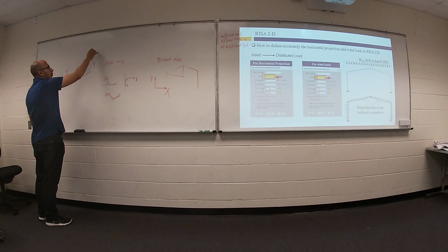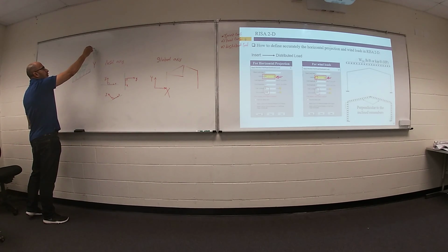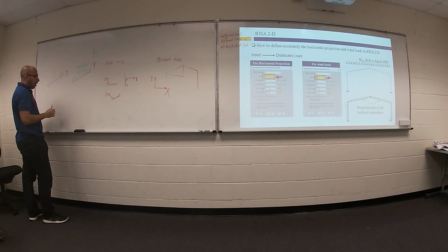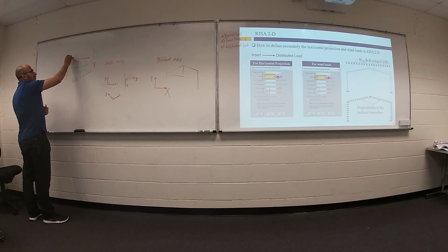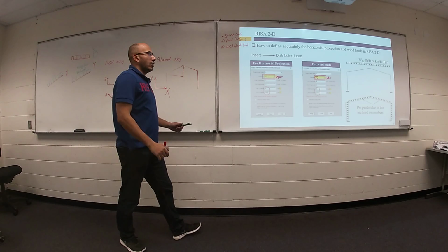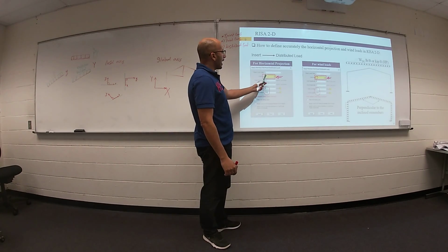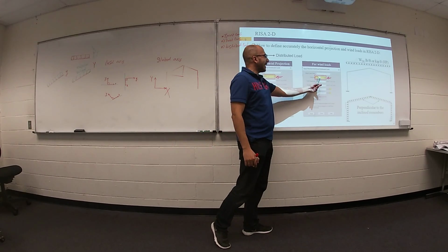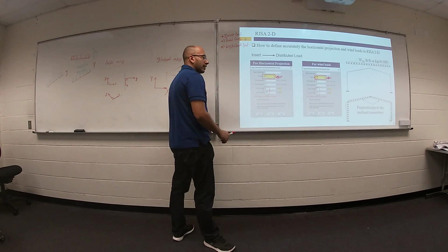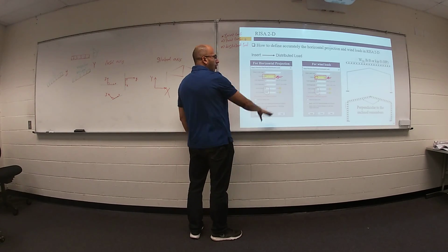What will happen if you choose Py? Py means projection in y direction. That means your load will be something like this. So, when you are defining your distributed load, you can choose which case you are working on based on direction. If you open this one, you will find many options.